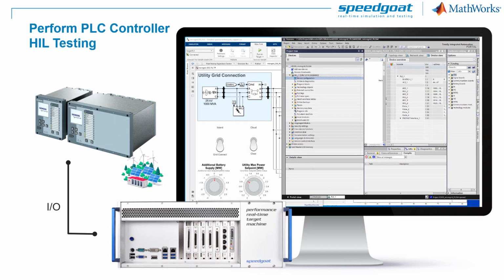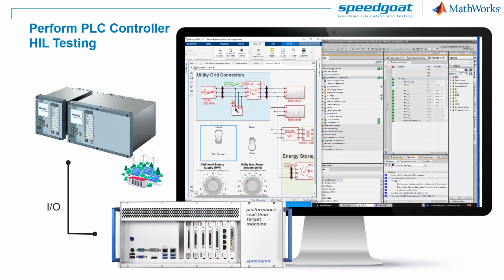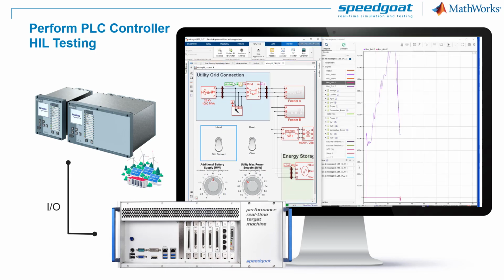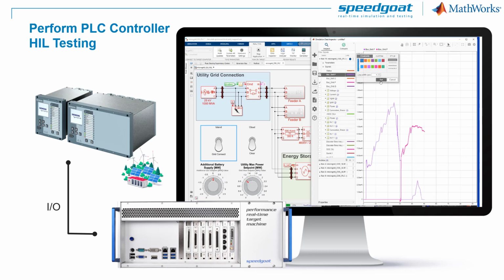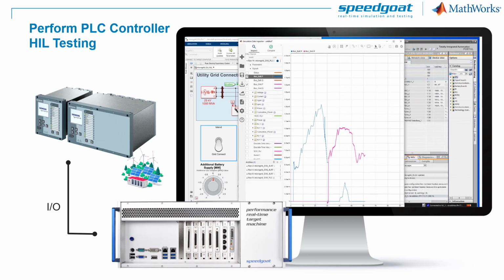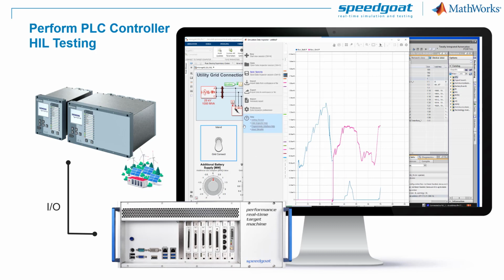Now you have your plant model, which represents your real system. From I/O level or communication protocol level, they're running in real time and they behave just like your real plant. The difference is your plant model is virtual. So when you hook up your controller to the target machine, it's just like you're testing your real system. And you can test them over and over again, and you don't need to be worried about breaking the hardware.